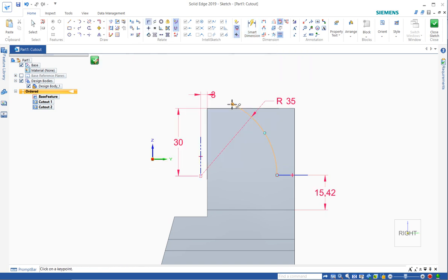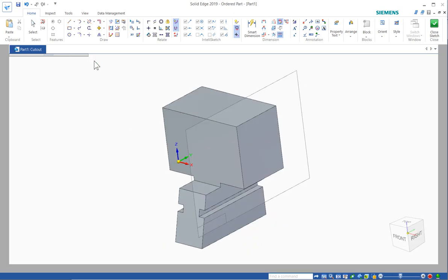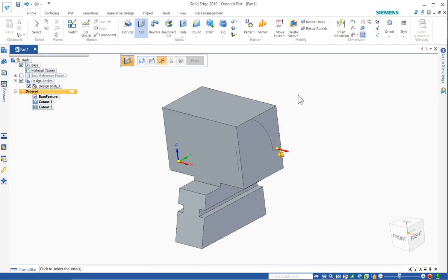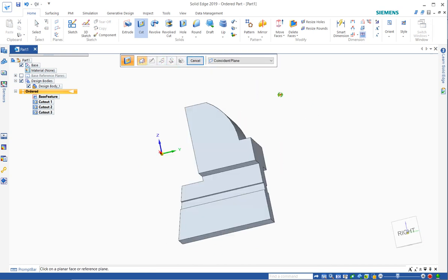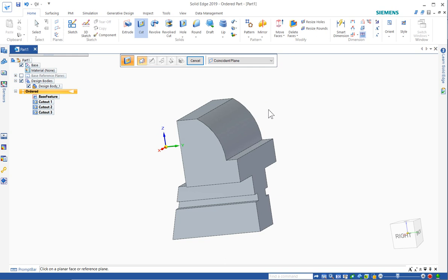It's not constrained at the top here. I think if you wanted to constrain this, you could click the endpoint in the top, and that's enough. And you could even do this endpoint, though it's not required. The software will extend that profile. It's going to ignore that dashed line and just treat this as a cutout, just like we did before.